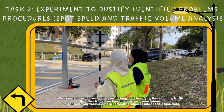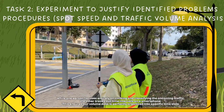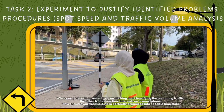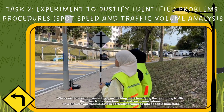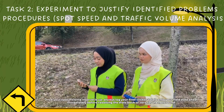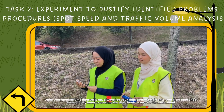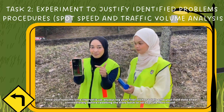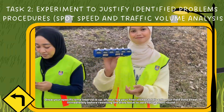While one person focuses entirely on filtering and classifying the oncoming traffic, the other tracks our time interval on a smartphone. This ensures our volume data is perfectly organized into specific time slots. Once your specific time interval is up, always log your final clicker totals onto your field data sheet immediately before resetting the dials back to 0 for the next round.